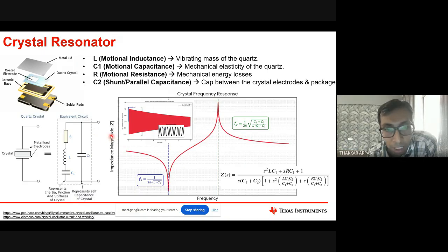What will happen is that as temperature changes, right, this is not going to change. But if your cross couple pair shows different GM for different temperature, this amplitude is going to be different for that temperature.